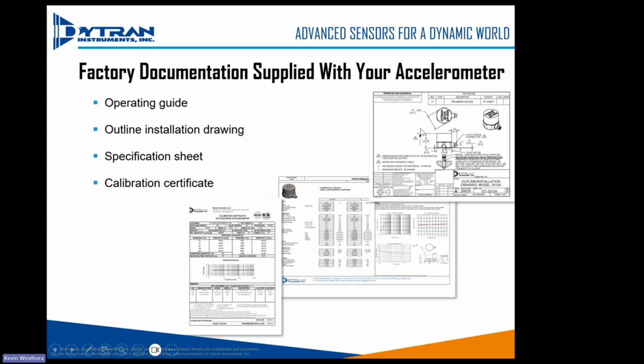So the first one is up in the upper right, called an outline installation drawing. It's what we call the 127 drawing of the sensor, and it has the dimensions of that particular sensor. It also includes any mounting conditions that would be included for that sensor, maybe the recommended torque, if it's stud mounted, and the surface finish preparation, if you're going to glue mount it or stud mount it, either one. So a very important document called the outline installation drawing.